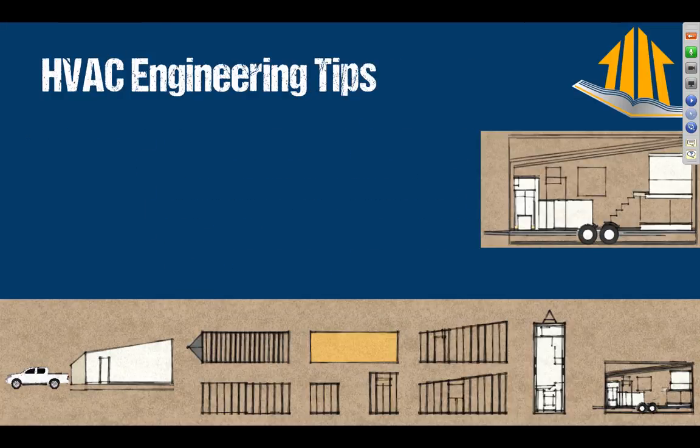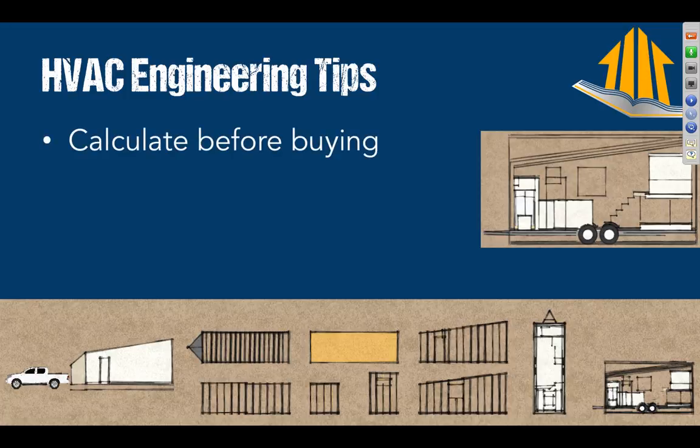Now, lastly, we're just going to go over the real quick tips. First of all, remember that you always want to calculate. Everybody wants to sell you something. They generally want to sell you more of whatever it is that you need, right? You don't buy shoes that are bigger than you need. You buy the shoes that fit your feet perfectly and make you feel great. So do the same thing with your heating, your cooling, and your ventilation systems. Remember that oversizing is very easy to do. People might not do it on purpose. The reason that you run the Manual J calculation, and remember that, write it down, is that it will help you to not do that.